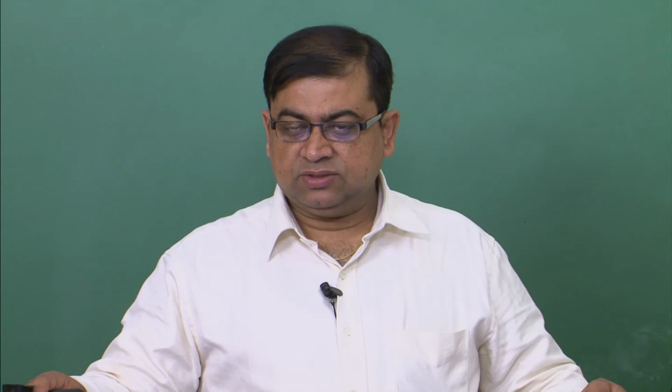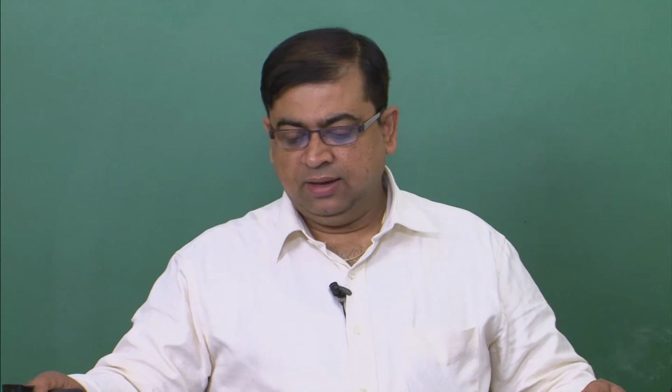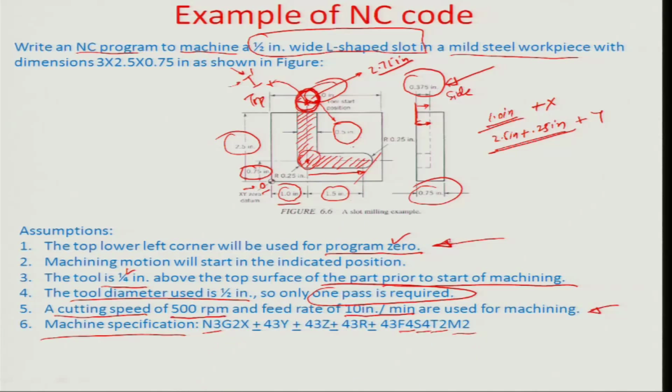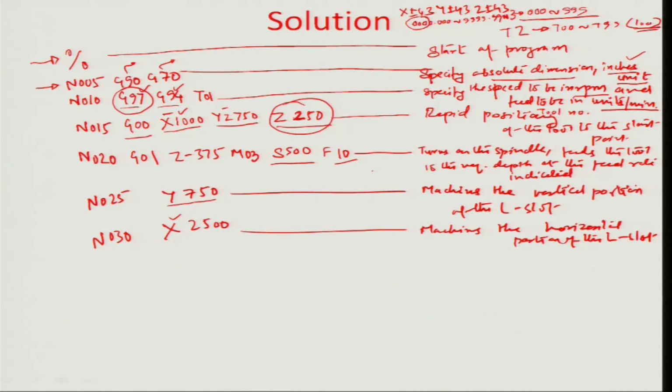align the tool in a manner so that you can retract the tool away from the position that it has finished in the last step. So the tool finishes somewhere here and is still rotating, and you have to somehow now retrieve this away from the block or the L slot so that the tool doesn't do any further damage to the system. So the next step therefore can be that first of all, whatever depth had been provided to the tool